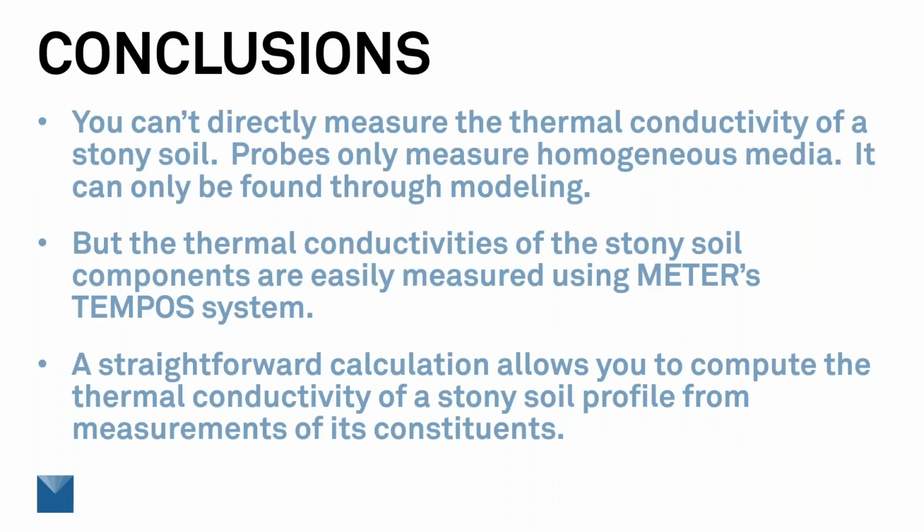So let me conclude with these thoughts. It isn't possible to directly measure the thermal conductivity of a soil unless you have a large budget and are willing to do a lot of work. Probes can only measure the thermal conductivity of homogeneous media. So the only practical way forward is to model it.